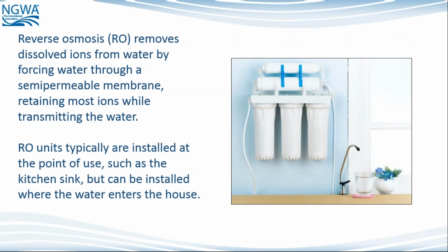With reverse osmosis, we actually apply a pressure to that process rather than just letting the pressure differentials be selected by natural occurrence. So we're actually forcing that water through the membrane and allowing the membrane to do that filtration.